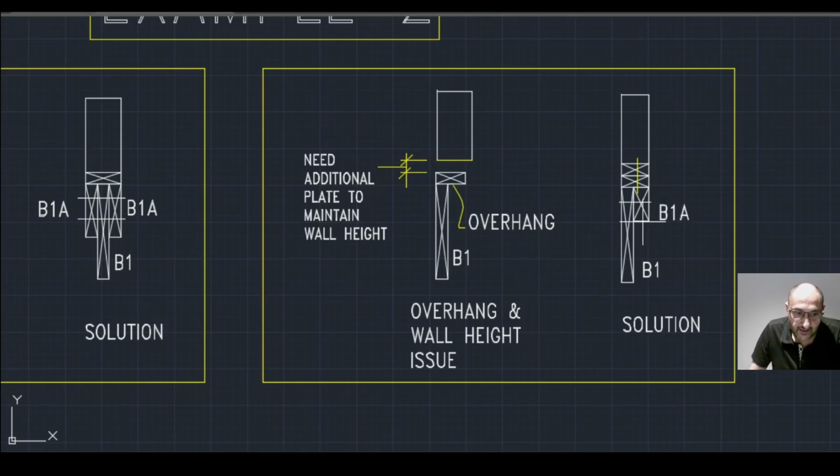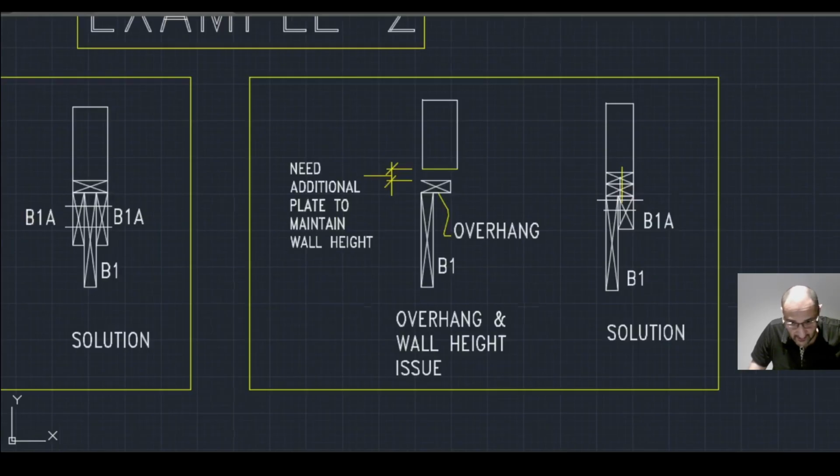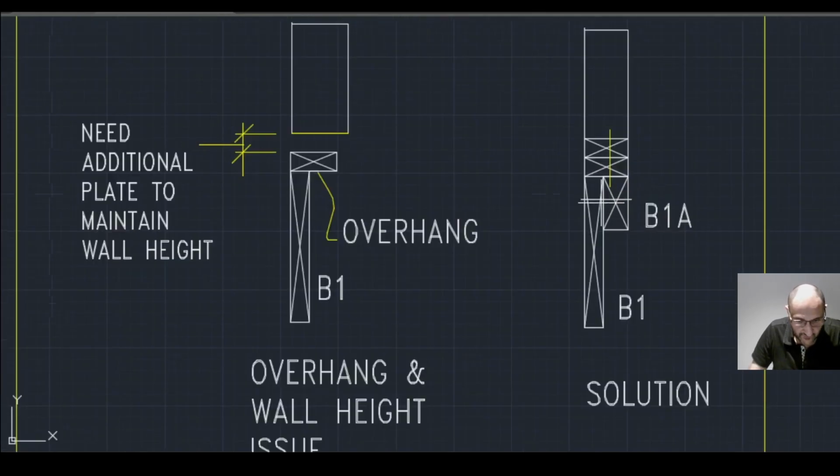In this case we need to consider the shear stress through the top plates and the beam separately. For the double top plates, the longitudinal shear stress is at this interface here, and the shear stress for the beam elements would be through this interface here.